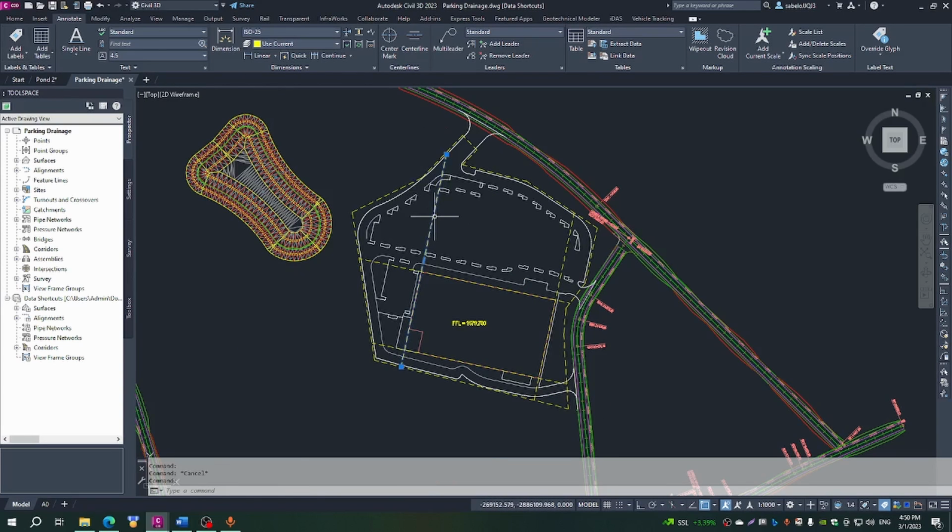What we have on our site is a number of polylines that we have drawn previously just to encompass the whole development area, and we just excluded those areas that tie to the existing external roads. We're then going to create a stepped-up surface that will define the drainage pattern. So these polylines, we are going to turn them into feature lines.